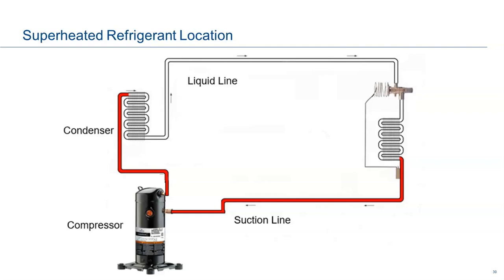So in other words, if you had 185 on your high side and 5 on your low side, and you were at your atmospheric pressure rounded up to 15, you would have 200 and you would have 20. You would take that 20, divide it into the 200, and you should come up with a 10-to-1 compression ratio. And that's just an example. I just plucked those numbers and used them as an example.